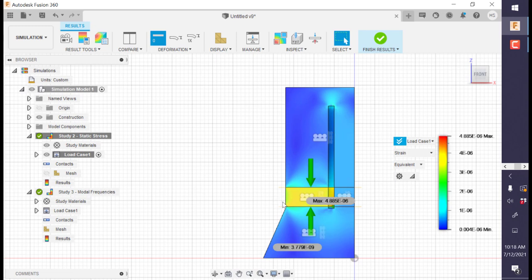and looking at the colors in this representation, obviously there's going to be the most stress, or in this case I'm showing strain, so we can also draw stress. There's going to be the most stress inside of the piezo because that's the way I'm applying and simulating the forces generated. Not using the piezoelectric effect here, I'm just simulating that using forces, which does add a bias force to your simulation. In order to better understand how the rest of the structure is dealing with this force,